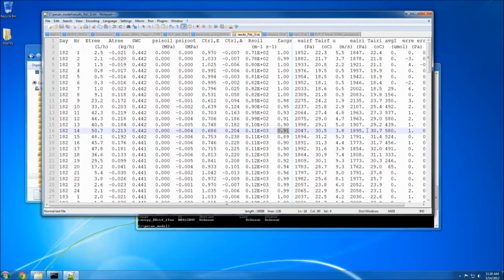And then for iterating the canopy conditions, it tells you, going over here, the water vapor partial pressure in pascals that is in the outside air, and then the value that is inside the canopy after the self-humidification from transpiration that's been iterated to convergence. It does the same thing for air temperature.